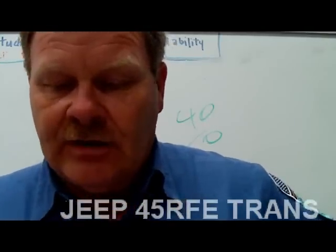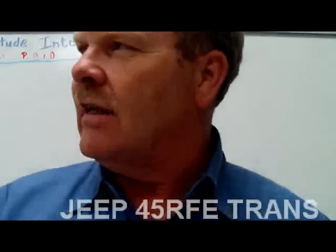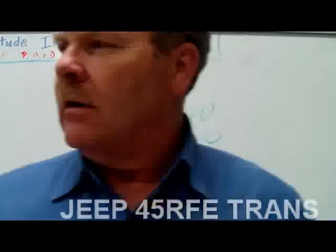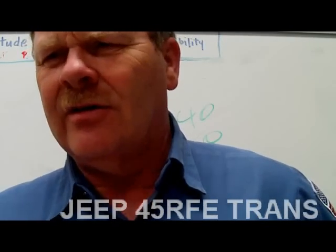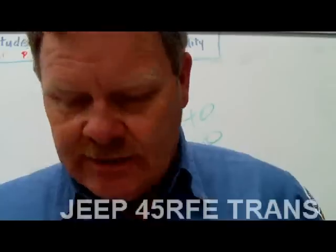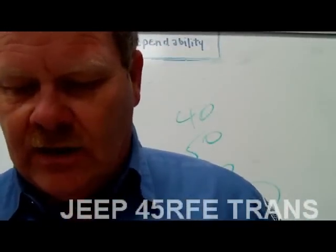But those speed sensors, those big plastic speed sensors, like to crap out too. They don't cost all that much, $30. That'll cause a van to be in one gear all the time. It can do that, yeah, but make sure you pull your scan tool and check that it isn't a blown fuse. Blown fuses can cause it to be in one gear all the time too. Yeah, that's what I told you. But anyway, there you go.